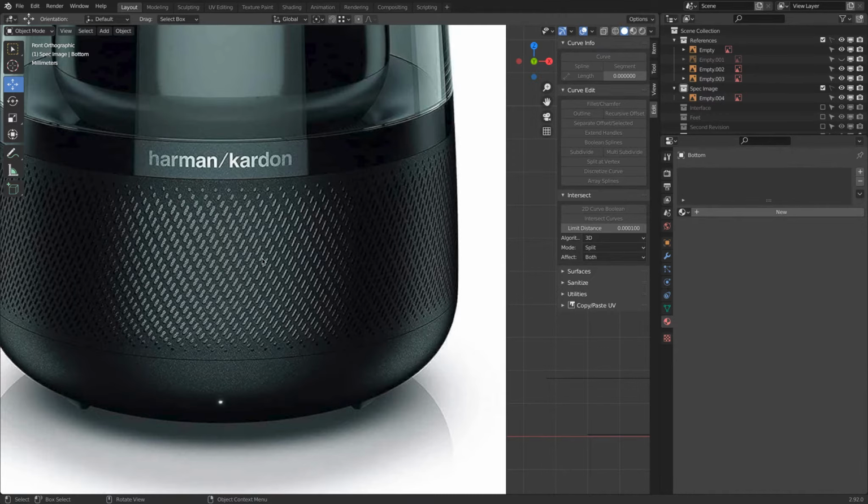And the structured plastic, the part geometry-wise also has these holes cut in. Now these holes we could actually model if we want to be crazy, or we could use a Boolean modifier. We model this pattern, rotate it, wrap it around and cut it out. Works, but is very labor intensive and thus slow. So I will show you a much faster technique to explore these patterns simply via texturing, using images.